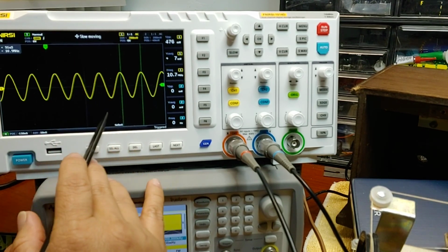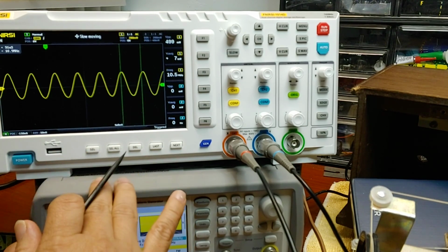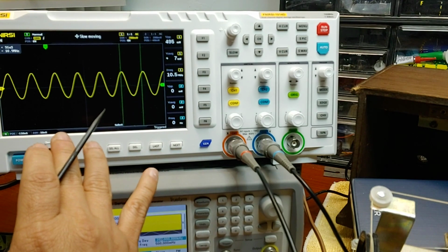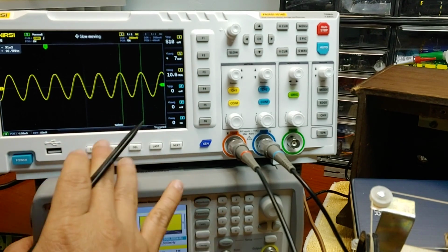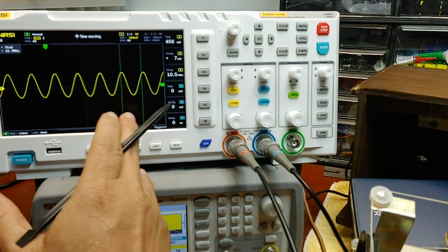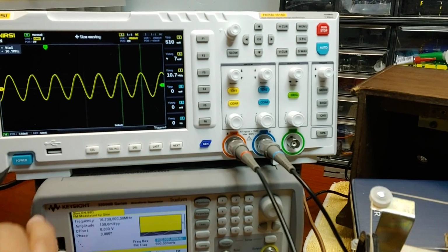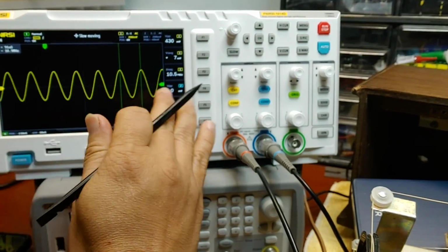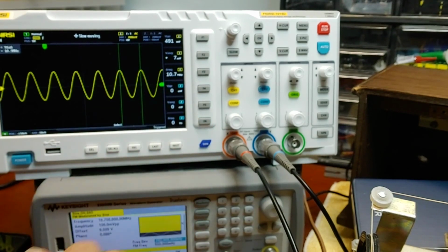And to see this, I set up the generator in slow mode, so the frequency actually varies over 0.5 seconds, so you can see the changing of the phase and magnitude. And I'm going to make a variation at 1 kilohertz, and we will probably hear the sound from the speaker. 1 kilohertz.